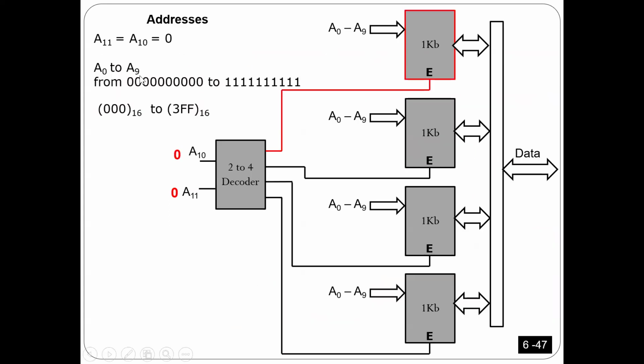The last thing I want to teach here, guys. Sometimes you can notice in your memory, you have to check, right? So maybe if you have 3 racks, you can put only 2 or 3 and so on. Okay. So that's what I want to show here: how I can use a decoder so that if I have 1 KB memories, 1 KB, 1 KB, 1 KB, how I can connect them together to create a memory that's 4 KB.